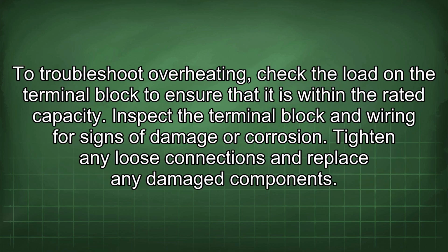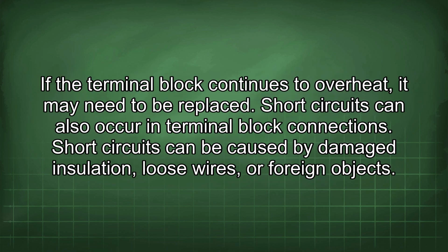To troubleshoot overheating, check the load on the terminal block to ensure that it is within the rated capacity. Inspect the terminal block and wiring for signs of damage or corrosion. Tighten any loose connections and replace any damaged components. If the terminal block continues to overheat, it may need to be replaced.